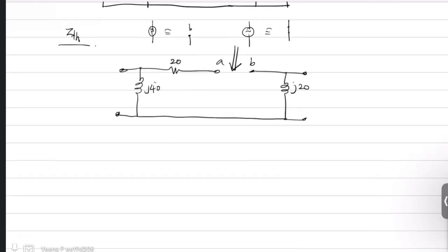What is the impedance when you look across this? When I take my A and B here, A will go to the resistor, then to an inductor, and B will go to an inductor. They both meet at, let this point be C. This is now a series RL circuit.